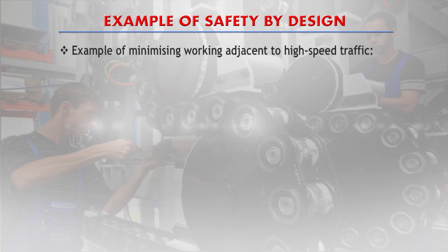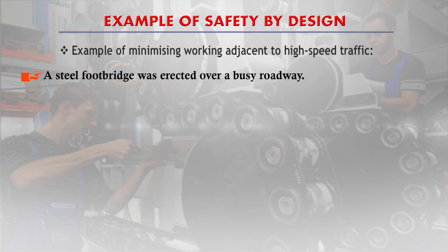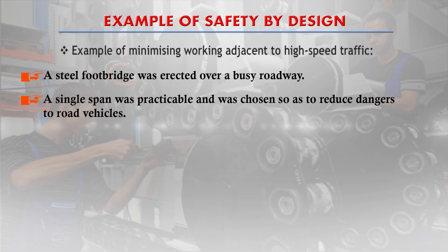An example of safety by design we can put like this. Example of minimizing working adjacent to high speed traffic. A steel footbridge was erected over a busy roadway. A single span was practicable and was chosen so as to reduce dangers to road vehicles.